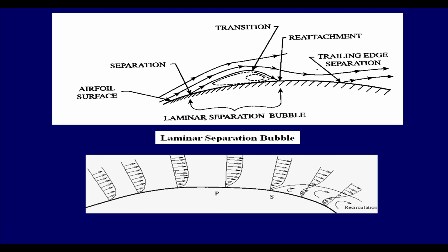So, that can lead to, again, massive degradation of the aerodynamic performance. So, one of the major research challenges in association with these kinds of flow regimes is how to tackle the laminar separation bubble, if possible eliminate it or keep it stably attached and things like that, so that the aerodynamic performance does not degrade.